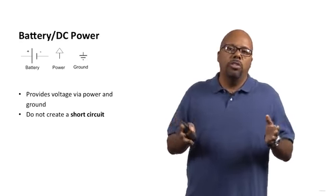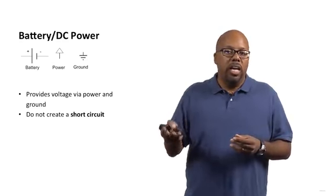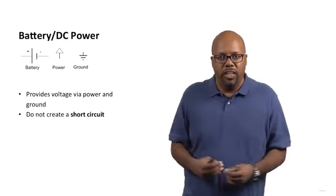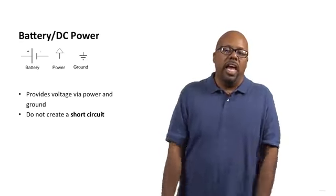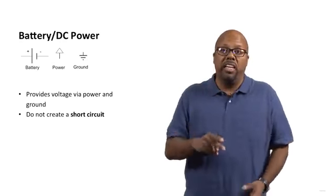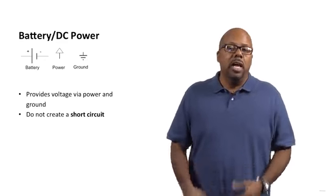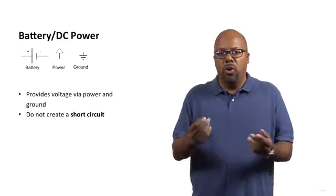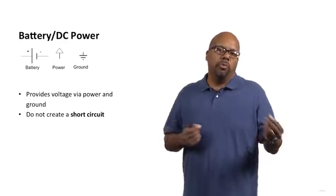Now, if we go back to Ohm's law, V equals IR, right? So I, the current, equals V over R. If R is close to 0, then I is infinite, or approaching infinity. What that means is if you short power and ground, you get a rush of current, and something literally smokes. You'll see smoke coming out of your board, you'll smell it, and it'll be extremely hot. It's not overly dangerous because we're dealing with low current levels, but you don't want to do that. You can mess up your breadboard too. It'll brown out a hole and might hurt it in the future. So never put a short between power and ground.